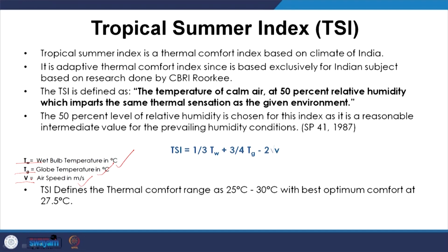So, through this, we are taking into account the adaptive thermal comfort. However, no specific consideration for the clothing value and the metabolic rate has been taken through the tropical summer index. Yet, because the tropical summer index is based on the study of Indian subjects, it is very close to the experience of tropical Indian subjects as far as thermal comfort is concerned.